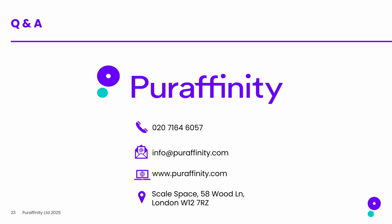Is there any leaching during application and at what level? It's the NSF certification. Obviously it would be to pass NSF 61. There's no leaching of anything that's hazardous. That's a concern. But just like every other material, activated carbon, when you first put it online, you have some arsenic leaching. The ion exchange resins, you have some organic leaching. So, we will meet the NSF 61 criteria.